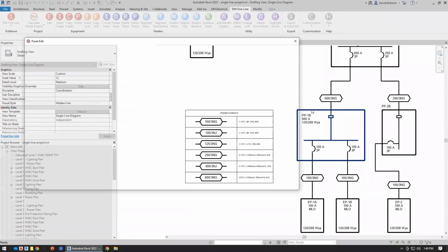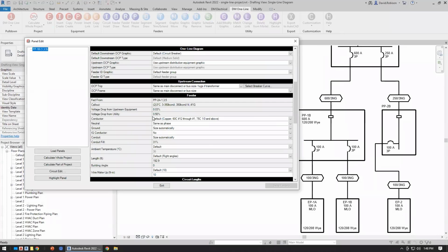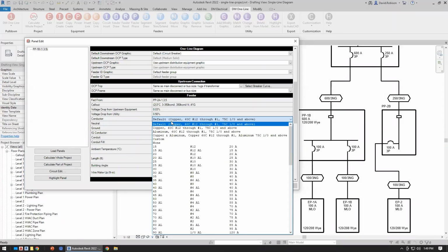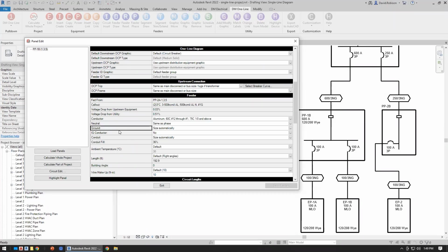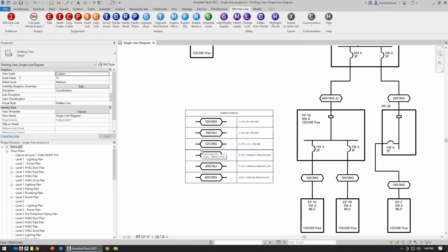If we go back to aluminum again, that exists in the master. It doesn't exist in the project at this point. We set it to pull from the master if possible. So I set this to aluminum. It's going to see that that exists, and it's going to pull it from the master, put it in the project for us. So it recreated that using that setting in the master. It doesn't match the default settings that we have. If we just had it Design Master generated, it would have done that -A. It didn't. It saw what was in the master and pulled it in for us.